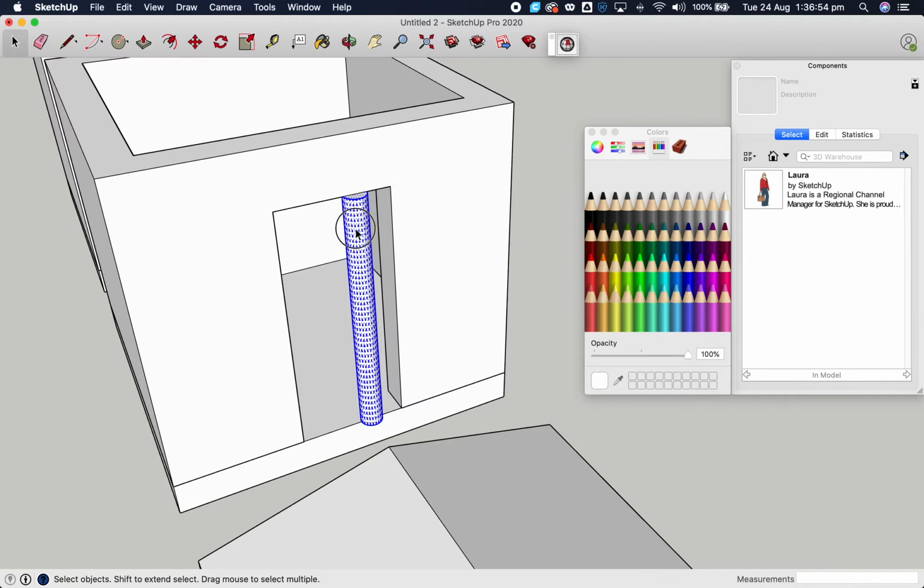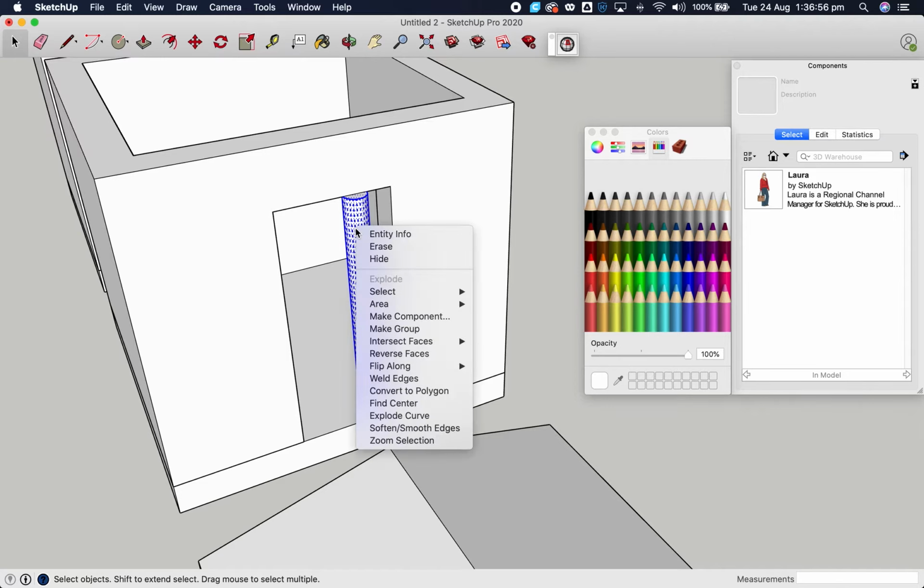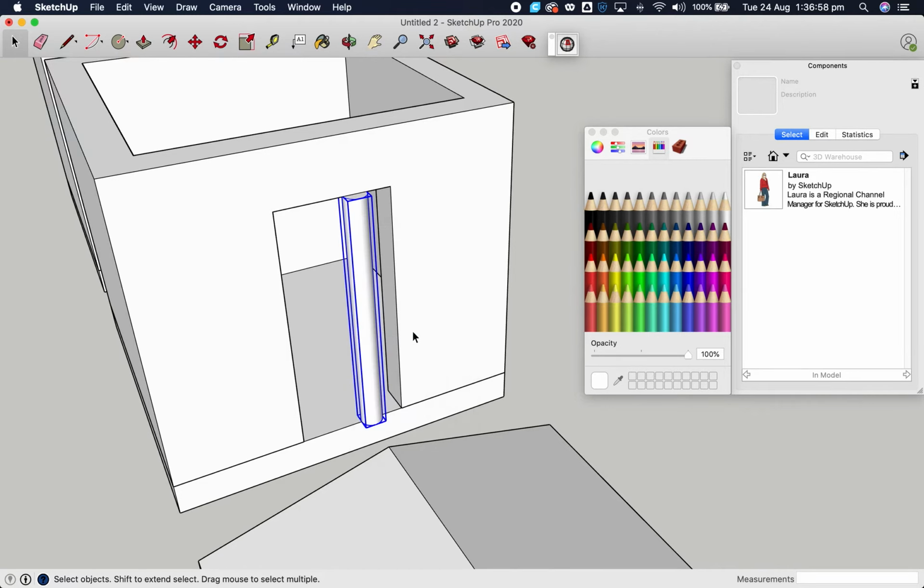Okay, and I'm going to triple-click on this, right-click, make as a group. Okay, and then I want this to be only 1 millimeter in diameter. At the moment, it is 2 millimeters in diameter, so I need to shrink it down. So I'm going to go to the resize tool. I'm going to reduce this down to 0.5. So now that is a 1 millimeter thick item.